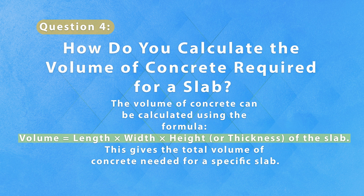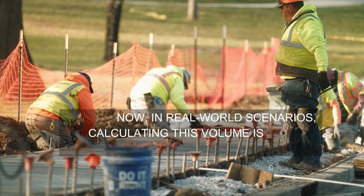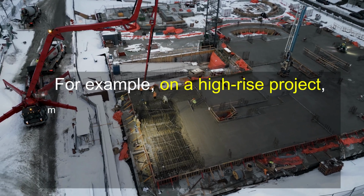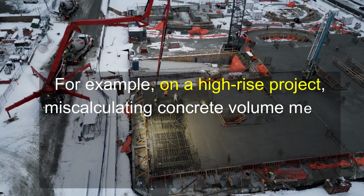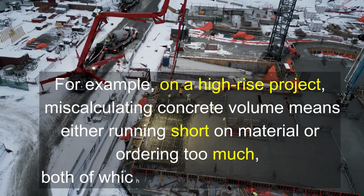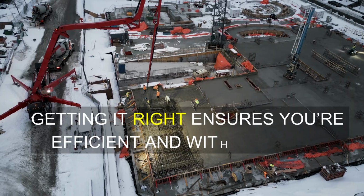The volume of concrete can be calculated using the formula. Volume equals length times width times height or thickness of the slab. This gives the total volume of concrete needed for a specific slab. Now, in real-world scenarios, calculating this volume is crucial for avoiding wastage. For example, on a high-rise project, miscalculating concrete volume means either running short on material or ordering too much, both of which can cost time and money. Getting it right ensures you're efficient and within budget.